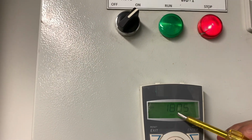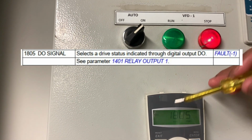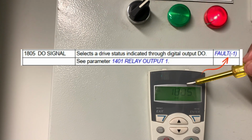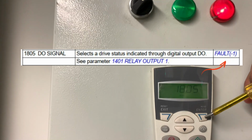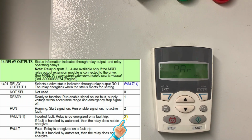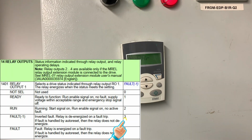After that, in 1805 you have to select the reason when you want this transistor output to be actuated. The first relay I have used for run status, but this one I will use as a fault. So for fault it must be 3. As you can see it's already set to 3. 3 means when my VFD gets tripped, the transistor output will get actuated.